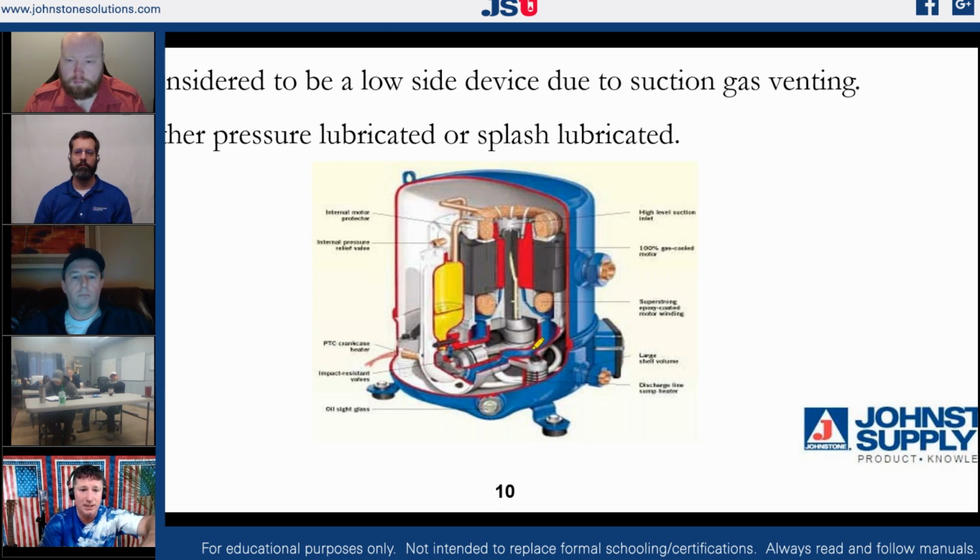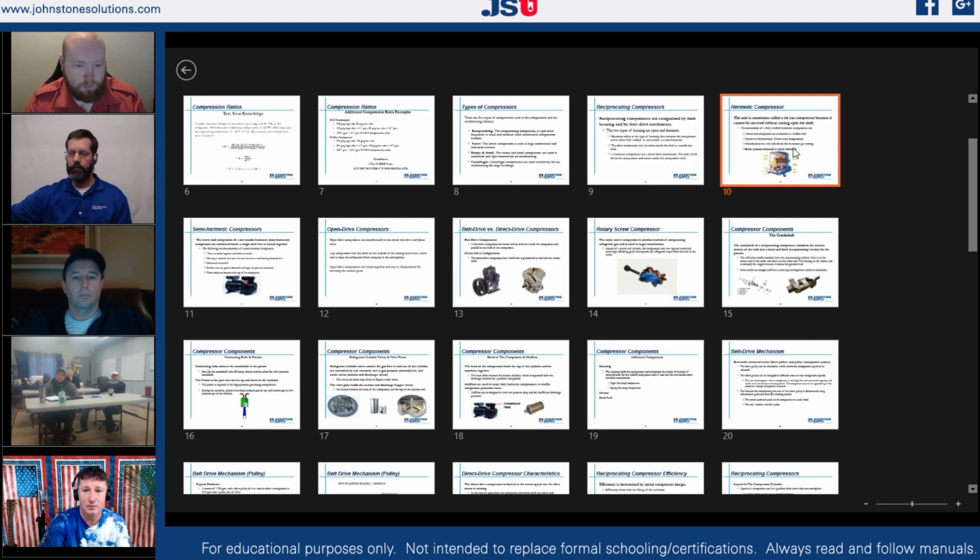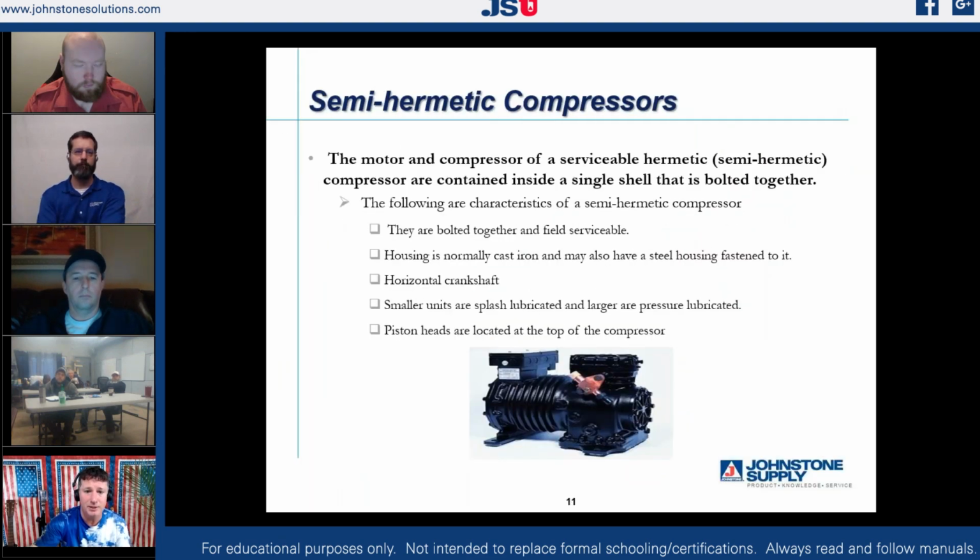So we're going to bring vapor in, it's going to pull it into the cylinder, our piston is going to compress it, and we're going to now discharge that out as a high pressure vapor. So pretty simple design, really, and that's why they lasted forever. You know, a reciprocating compressor, when properly operated, lasted for decades. So very good compressor to have.